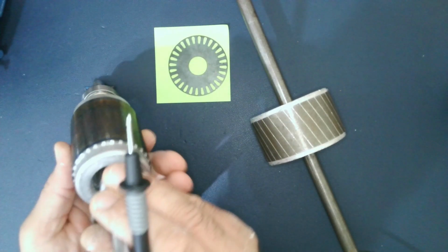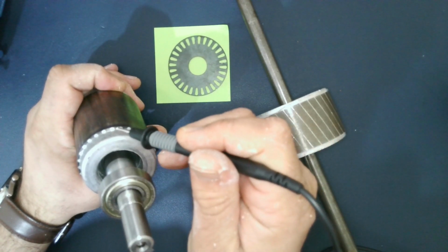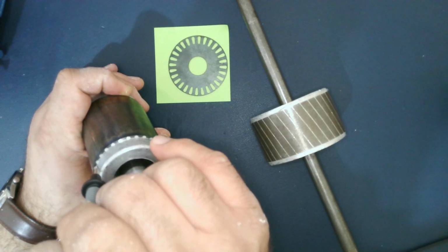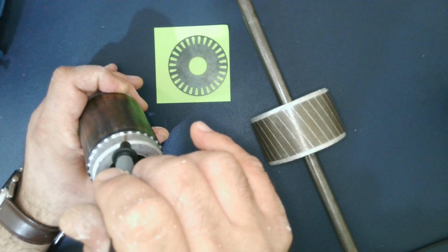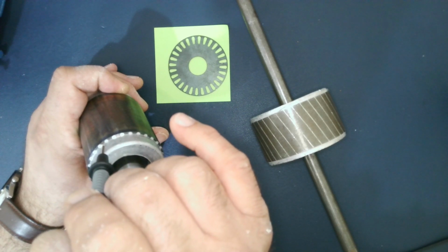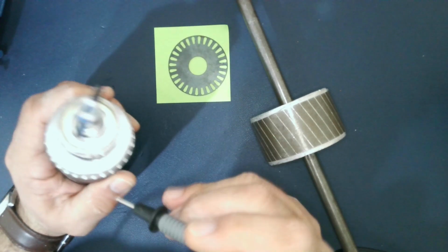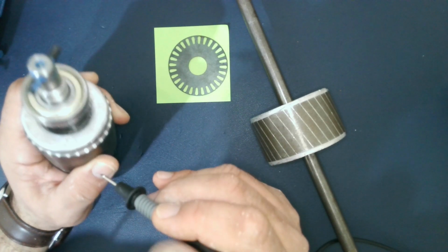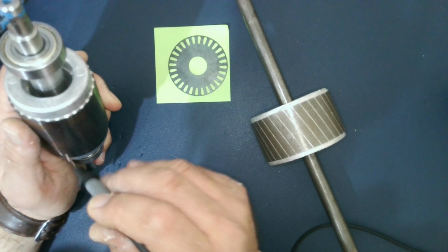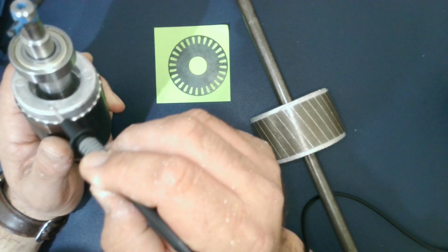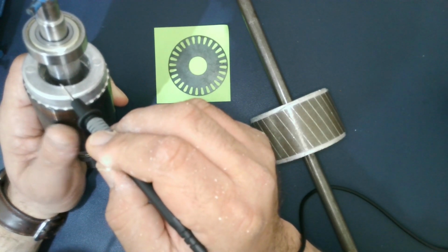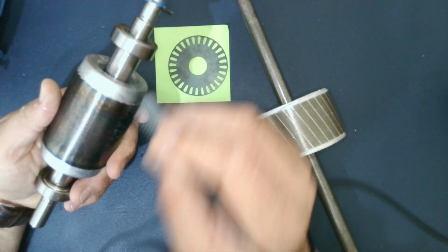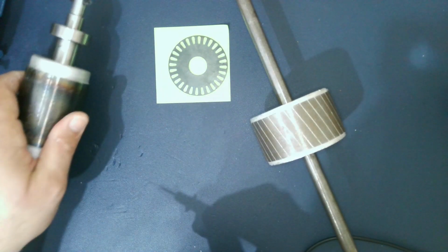If we look deeply here, we are going to find that the slots or these bars are on the surface. So these are the slots, as we can see here, and these are the conductive bars. From the other side, you are going to see the conductive bars here, and they are in some slots. They are in a straight line, they are not skewed. And we have end rings on this side and another end ring on this side. And we have a bearing on the left side and a bearing on the right side.